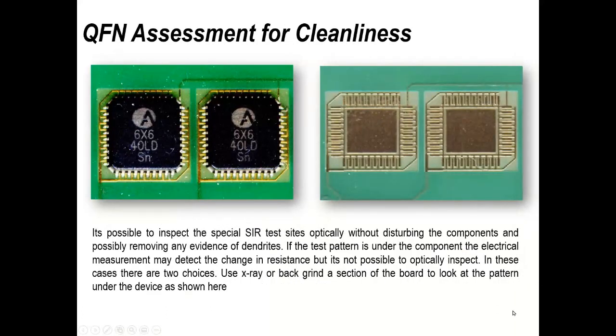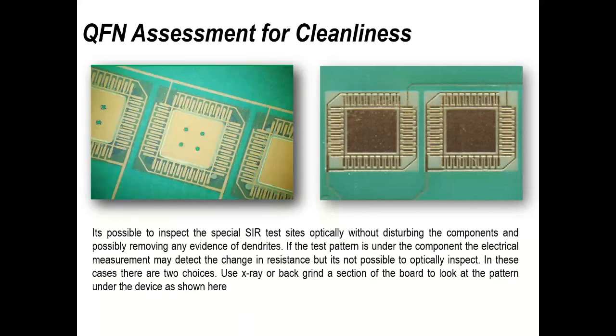Now, I've mentioned microsectioning and samples, etc. I just thought there was an opportunity to show a few other things that we could do, a few other techniques, and these are QFNs. Now, you can microsection in the traditional way, cut through the solder joints, etc. But there are other things you can do with a microsection or the potting of a microsection to help you understand and look at certain aspects of manufacture.